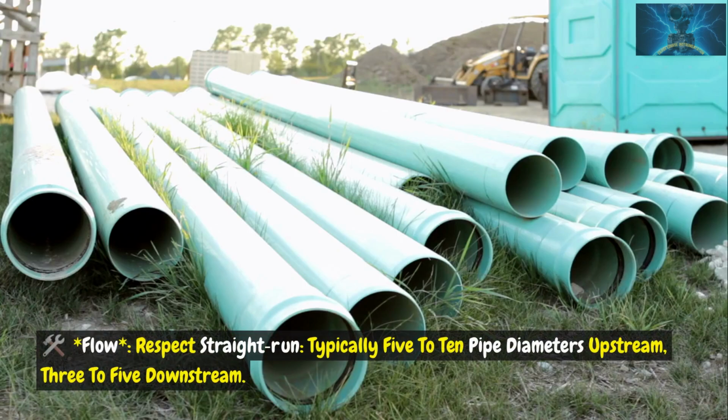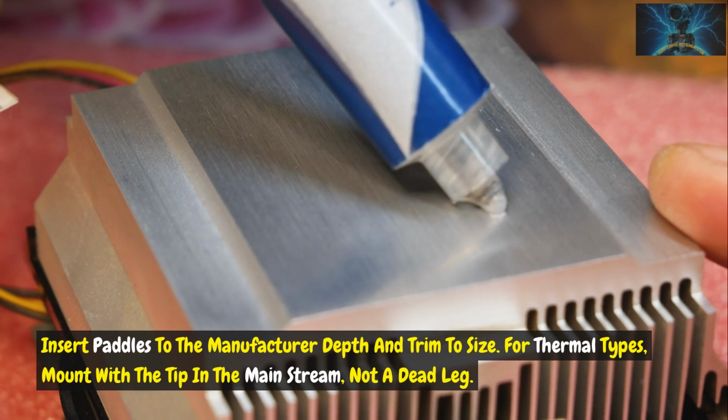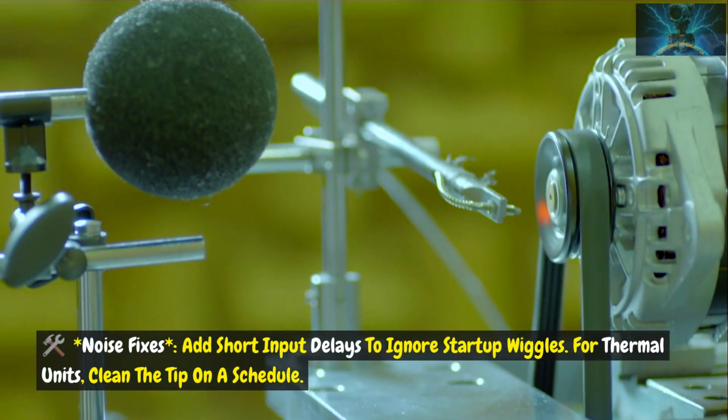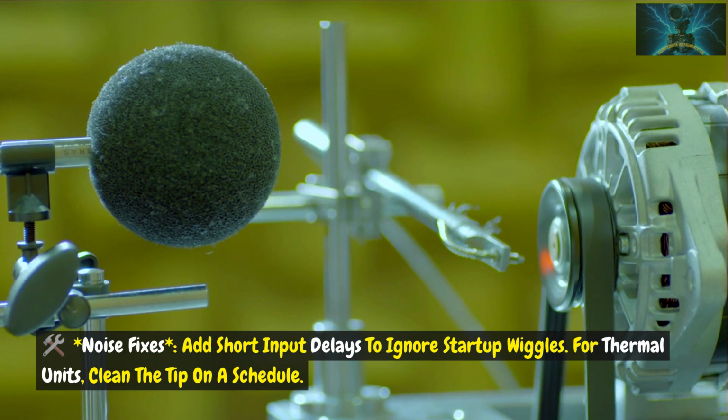Flow: respect straight run, typically 5 to 10 pipe diameters upstream, 3 to 5 downstream. Insert paddles to the manufacturer depth and trim to size. For thermal types, mount with the tip in the main stream, not a dead leg. Noise fixes: add short input delays to ignore startup wiggles. For thermal units, clean the tip on a schedule.